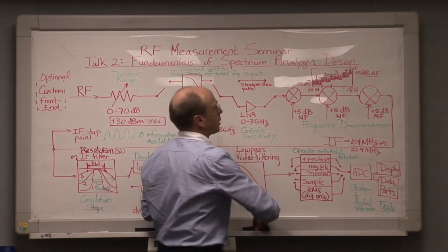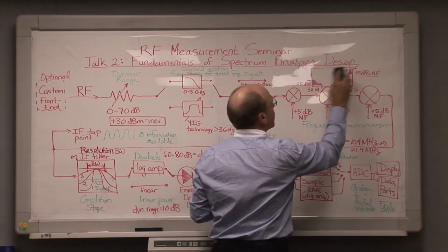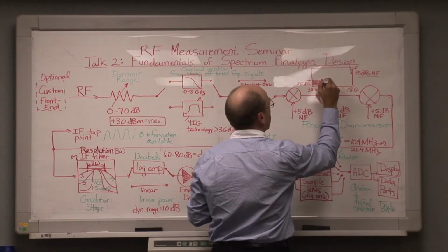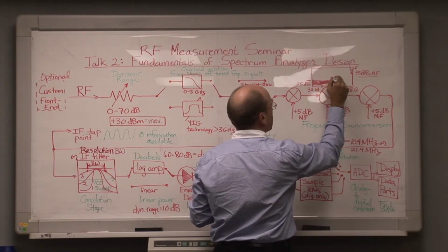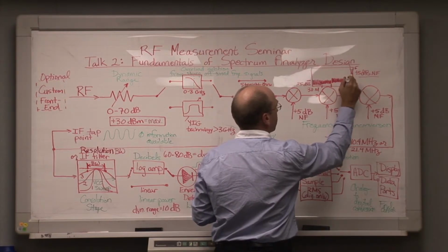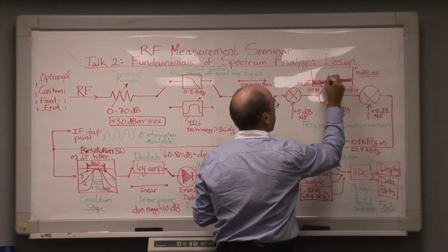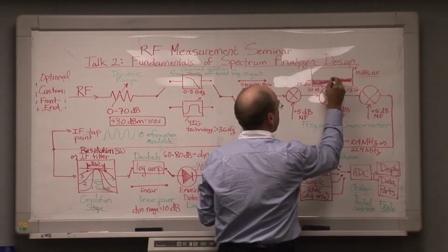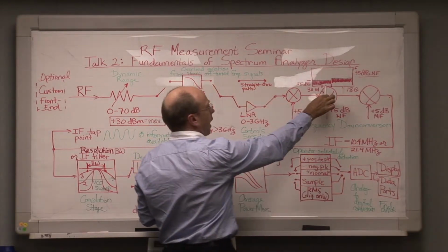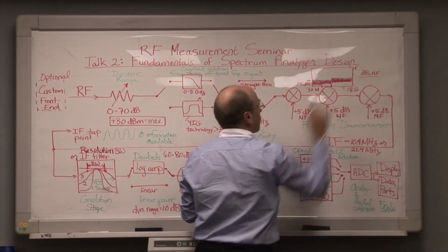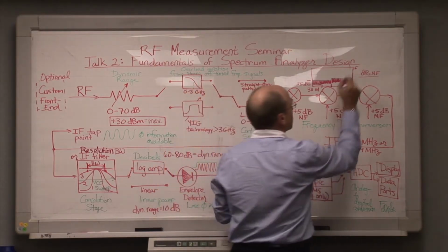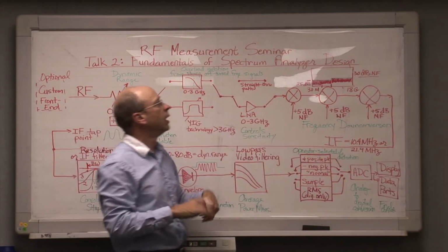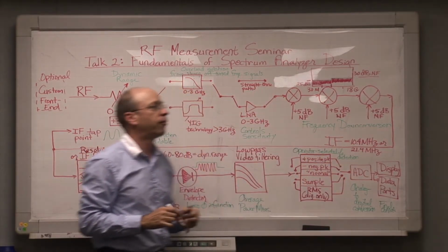In newer spectrum analyzer designs, where fewer stages of mixing are required to reach high frequencies, we may find that in fact we have only about one stage of mixing to get ourselves up to the highest frequencies, and so we end up with some of the newer spectrum analyzer designs having a 25 or so dB noise figure at lower frequencies, and then only about a 30 dB noise figure at the higher frequencies. And this really does represent an improvement in spectrum analyzer design that's been made in the last 10 years or so.